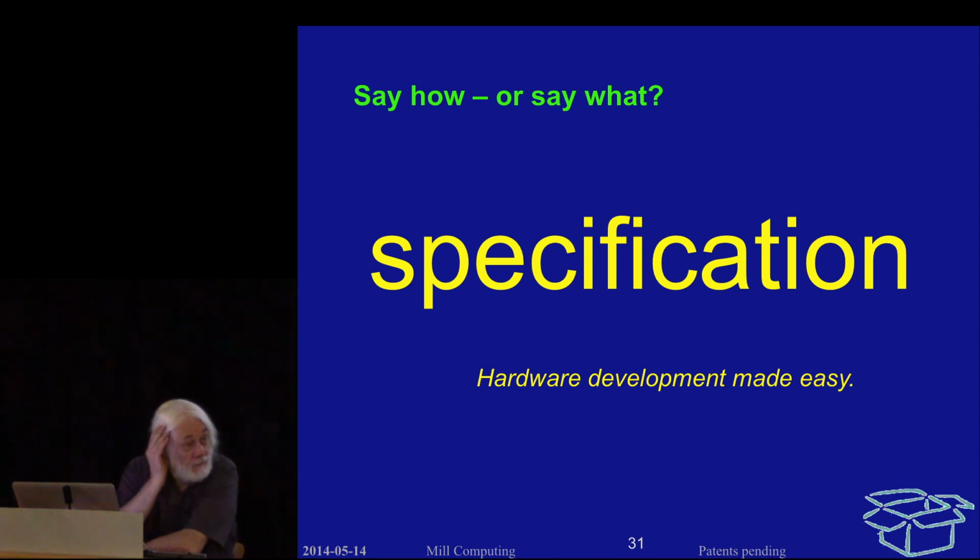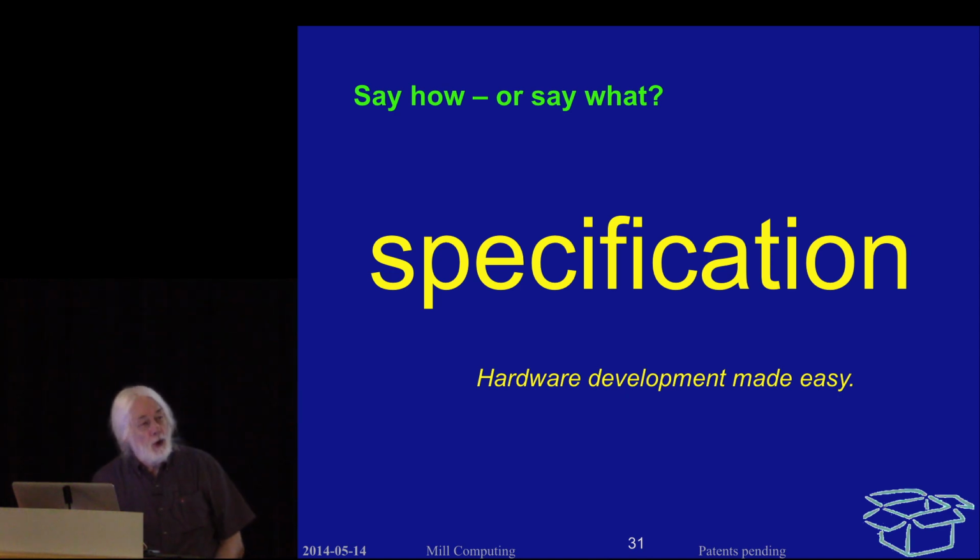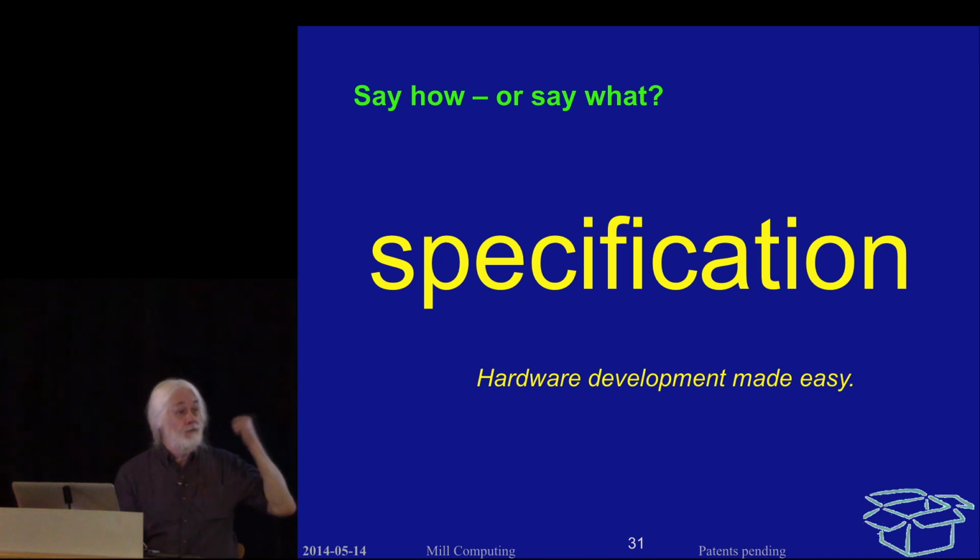Do you do any optimization on all the ops you create, unique or one substitute can? There's some very interesting code in there. The bin packing problem, that is to lay out all possible combinations in the most dense way, is NP complete, NP hard, NP something. In fact, the numbers are small enough that we actually do use an internal exponential algorithm, because it's going to be replicated across millions of chips. And this is why it takes 20 minutes to build a new member, because it is in fact doing the NP complete perfectly dense encoding as it figures out which bits mean what.